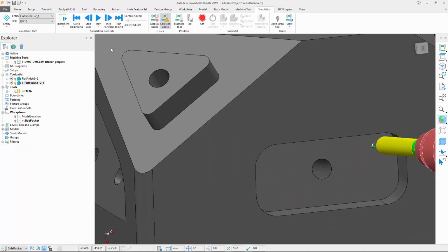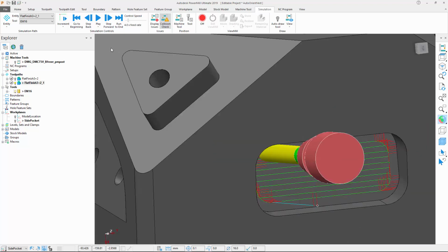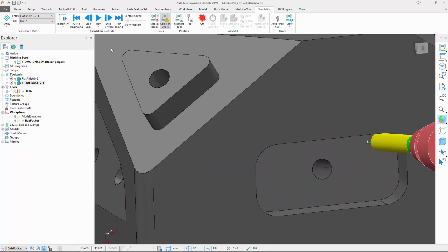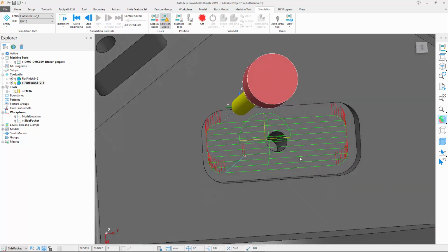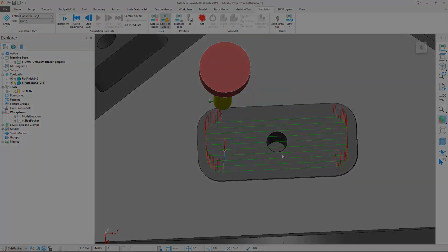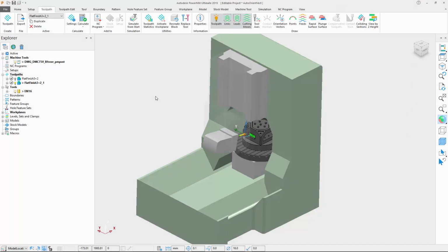It is worth stressing that, as previously mentioned, with an appropriate option file, these changes will be passed to our output file, meaning the simulation and post-processed output are more likely to match each other. It is important to specify that the orientation vectors will only be set when a machine is used for simulation or NC program verification purposes, and the toolpath takes the machine out of gimbal lock, which means 3-axis toolpaths won't be assigned orientation vectors. Furthermore, it must be underlined that the improvement will not work if WS model is set as the solver associated to your MTD.